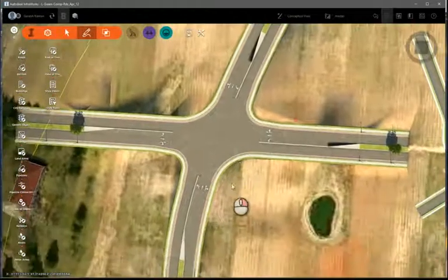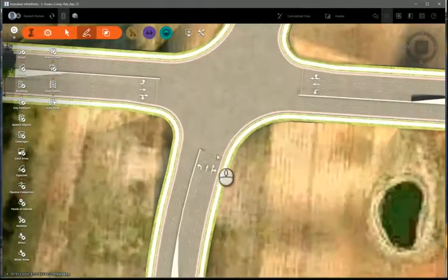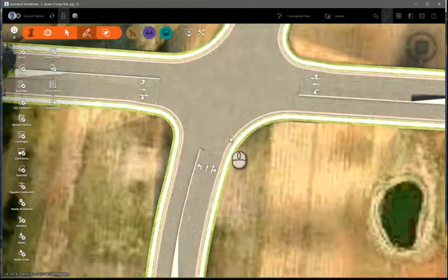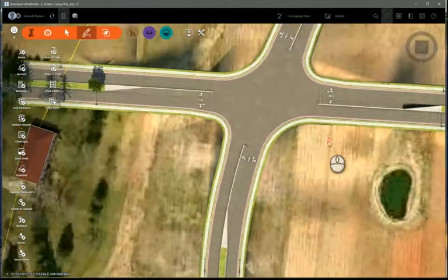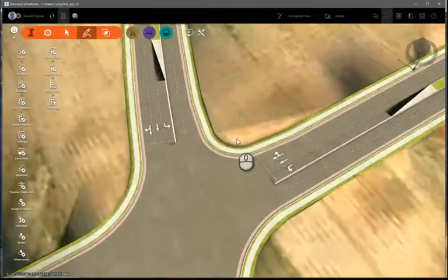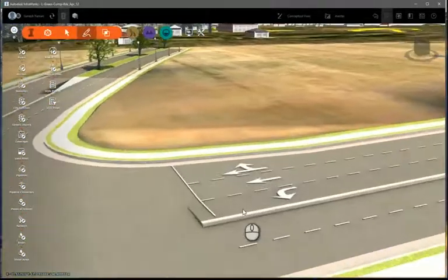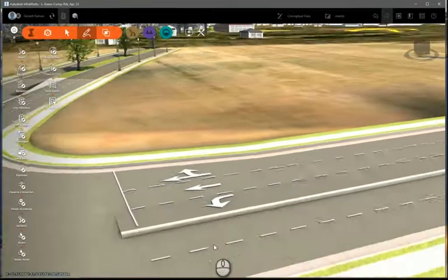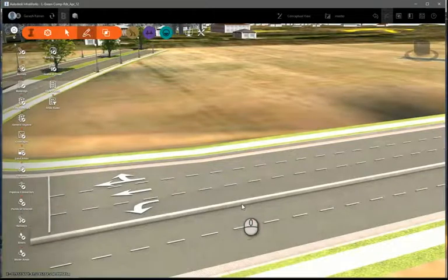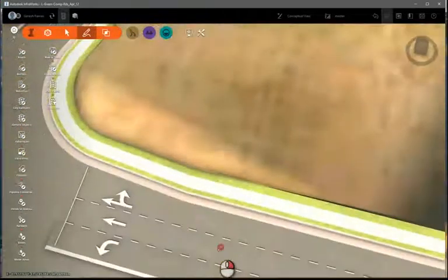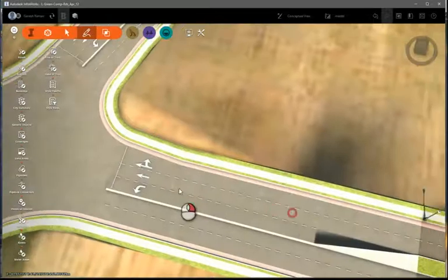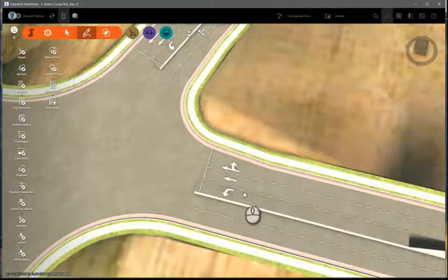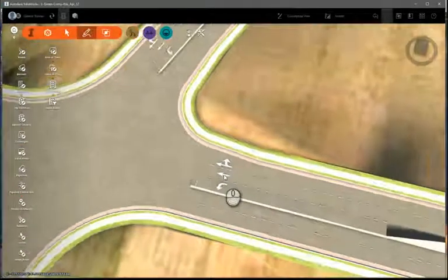Now, all the through lanes match. The right turn can also be made from the rightmost lane into a matching lane over here. So if I zoom into this in 3D, you can see that there are some issues here, which is because of the curb. And in our case, we will be changing this curb into a double yellow line, and we'll be changing this from a 2-lane to 3-lane into a 1-lane to a 2-lane with a dedicated left lane and a through lane.